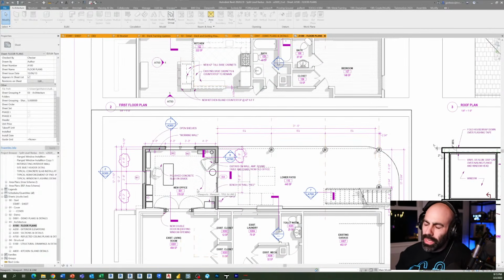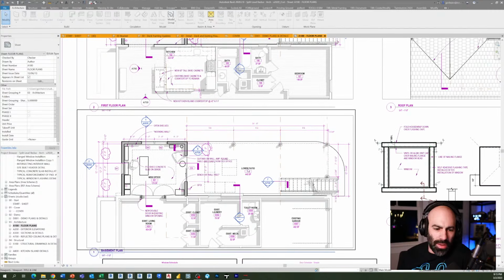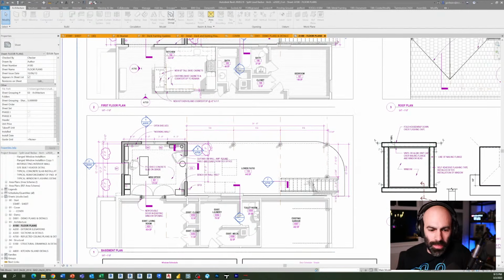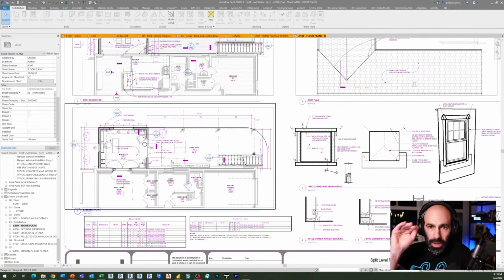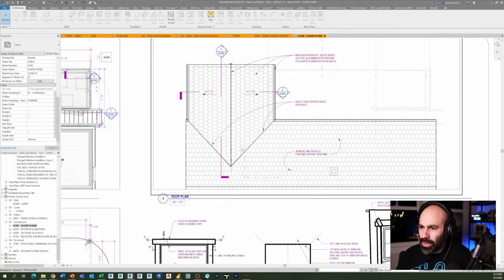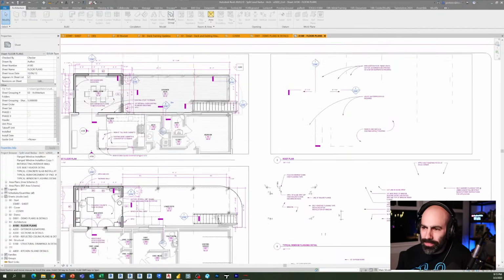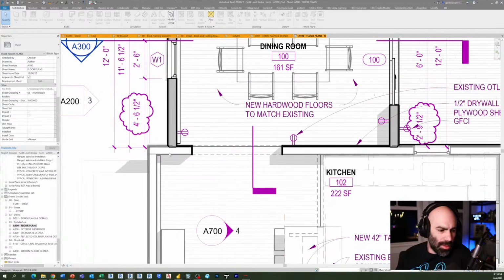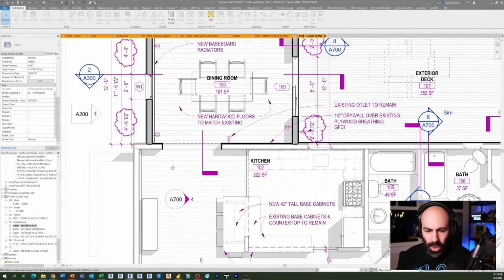So a nice little small addition, with the idea also to have a space underneath the deck, which I also ended up putting under decking so that it was a waterproof space as well, and then keeping the roof as simple as possible, with just a nice little gabled end. Notice I sucked in the corner of this. I was planning on changing materials, trying to make the roofs join nicely. Whenever you have something turning or joining like this, it's always nice to have a little relief in the corner, and that helped a lot constructability-wise too, which was awesome.